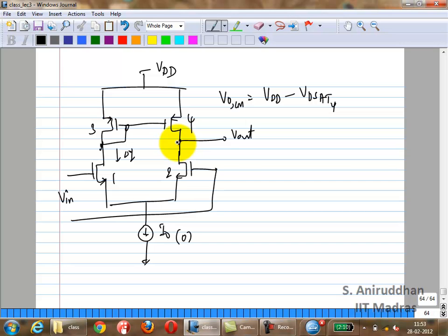So in general, if you have circuits like this, you will need to apply some kind of common mode feedback to set the output DC voltage very well. Okay, we'll discuss ways to set the common mode pretty well later. Okay.